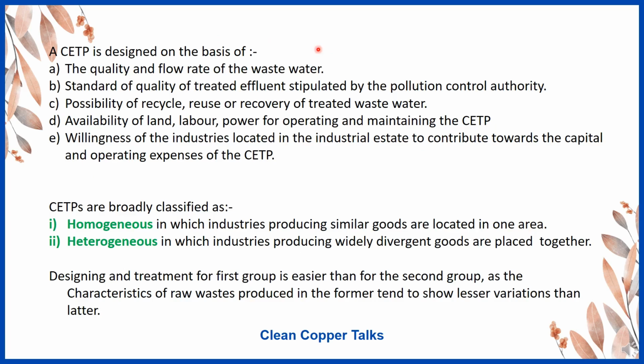Now CETP is designed on the basis of the following points. What is the flow rate and quantity of wastewater to be treated? This will depend upon the number of partner industries which have signed to send their wastewater into a CETP. The standard quality of treated effluent is stipulated by the Pollution Control Authority. What are the discharge norms on the basis of which the effluent treatment plant should discharge the wastewater? Based on that also the CETP is designed.